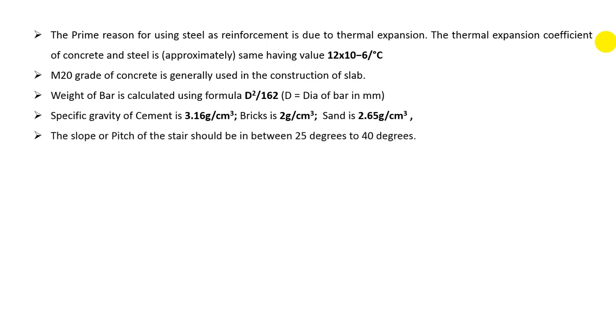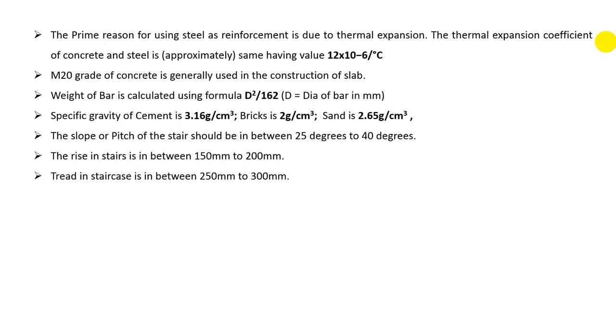The slope or pitch of the stair should be between 25 degrees and 40 degrees. The rise of a stair is between 150 millimeters and 200 millimeters, and the tread of the staircase is between 250 millimeters and 300 millimeters.